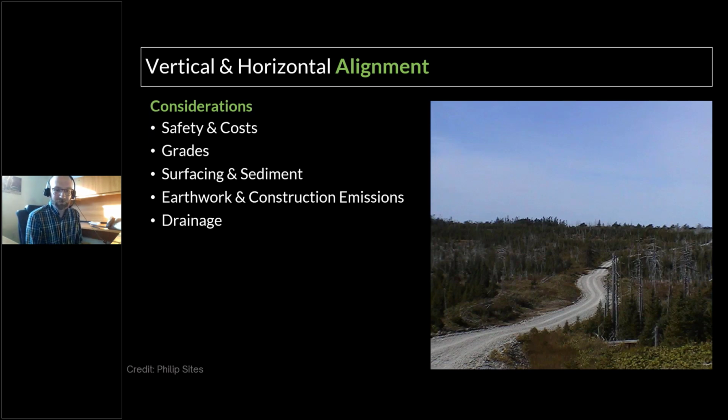Similarly, changing one design parameter often makes it necessary to change others. So for example, it's very common to change something like a cut slope angle, ground type, template, or maybe you change your stripping depth and suddenly you realize your alignment's no longer in the best location. And I mentioned that with the stripping, if you remove the material that's not being accounted for in your subgrade, you want to probably drop that down to get better balanced cuts and fills.